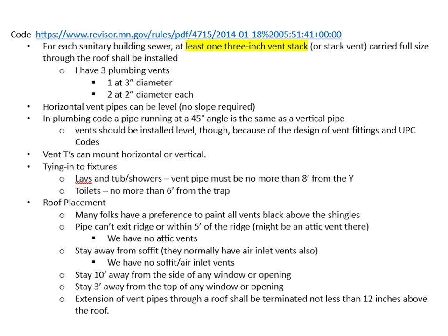Roof placement. Many folks have a preference to paint all vents black above the shingles. Vent pipe can't exit ridge or within 5 feet of the ridge. Might be an attic vent there. In my construction, we have no attic vents. Stay away from the soffit. They normally have air inlet vents also. We have no soffit or air inlet vents.